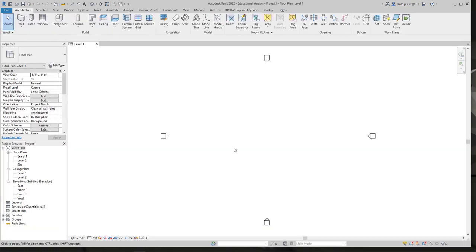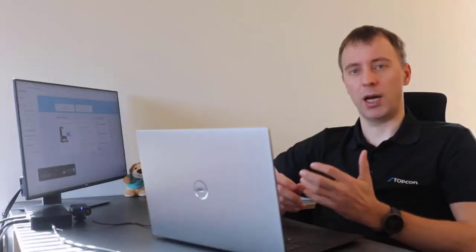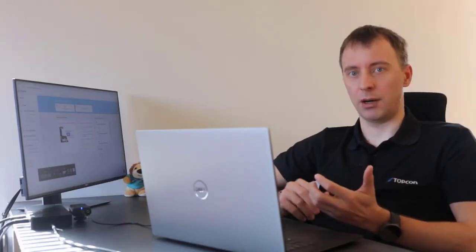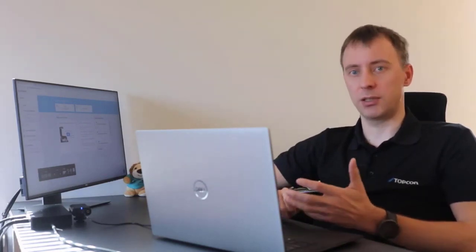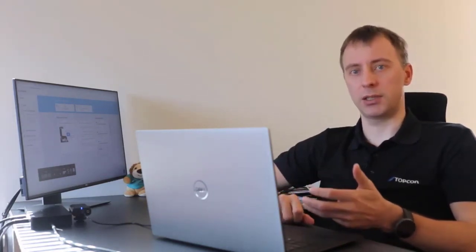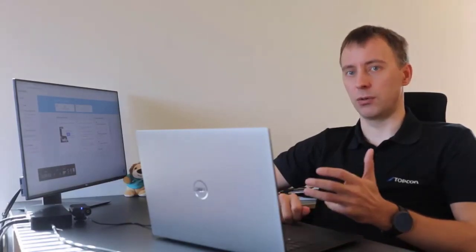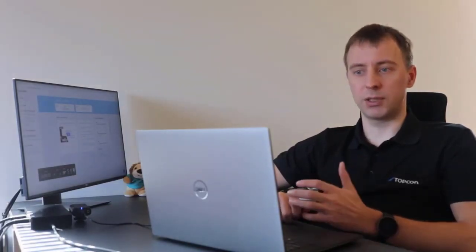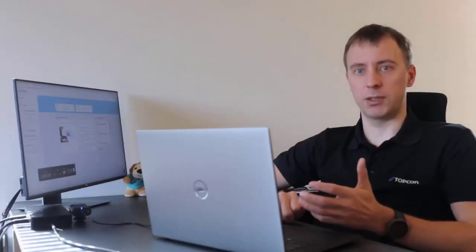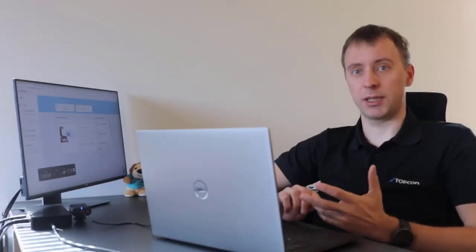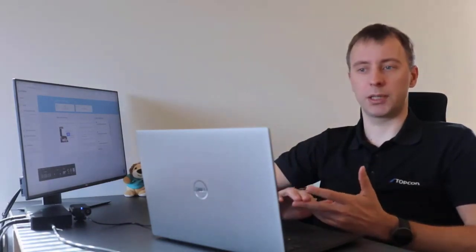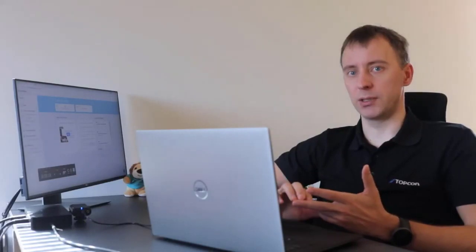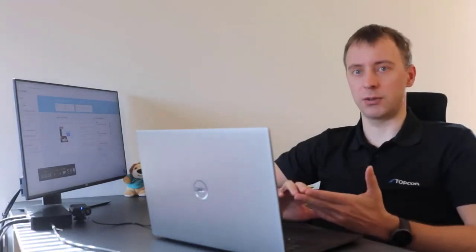So in that way you can do an Autodesk Revit 2022 installation. You have multiple ways to do that. Like Webinstall, which I don't recommend, only in those cases when you really need a quick installation and you also ensure that those options that you need are available in that Webinstall. So my recommended option is that you use Download Manager, but also if you need to install a product multiple times into different computers, then this custom installation is also really good.